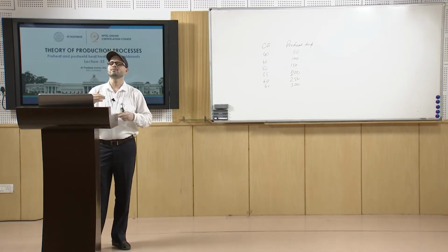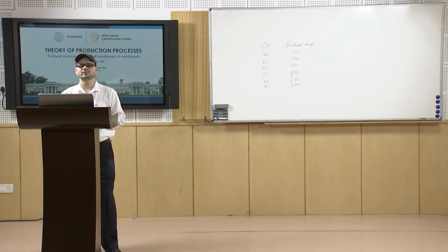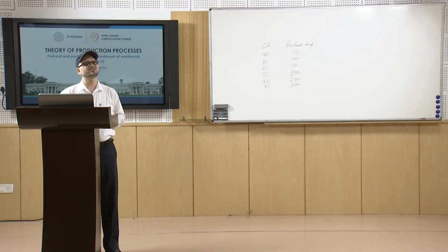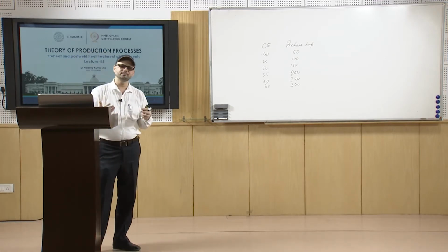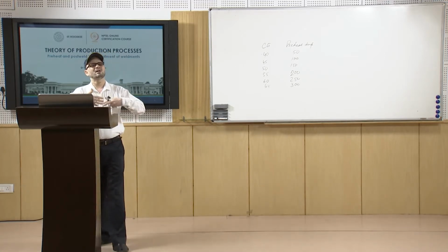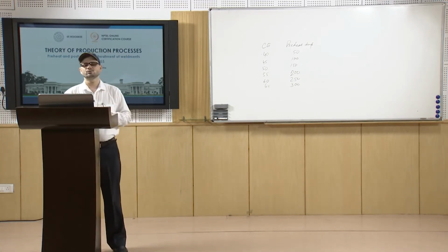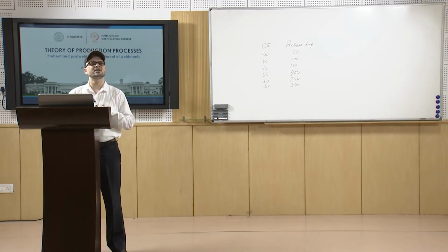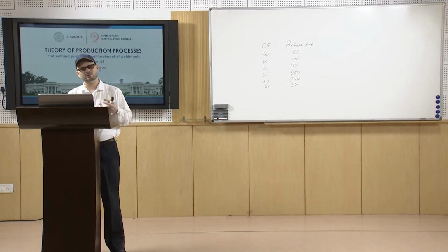So, we find the composition parameter, and the composition parameter is a function of the percentages of the alloying elements. So, percentage of carbon plus the other alloying elements. For silicon, divided by 30, for manganese divided by 20, like that.